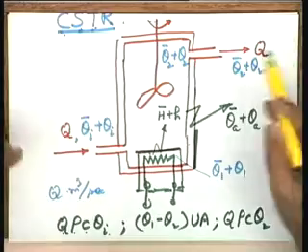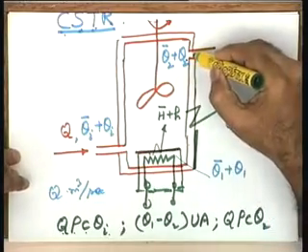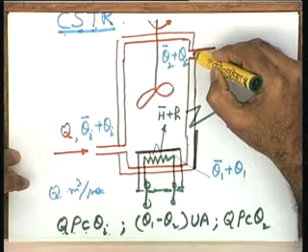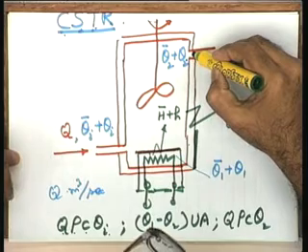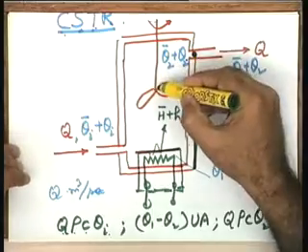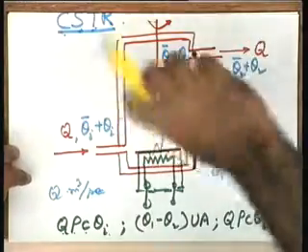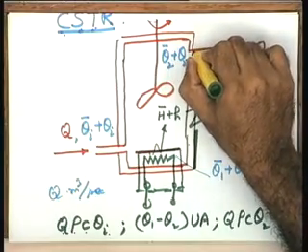What is the controlled variable? The controlled variable is of course theta 2. So, if I put my sensor here, I need your attention please. In that particular case, what will happen? My sensor, let us say thermocouple. The thermocouple output you know is in millivolts, very small voltage. Now, if the stirring here, vigorous mechanical motion of the liquid is going on, because of the vibrational effects, the noise signals will be produced, and these noise signals will be high frequency signals.